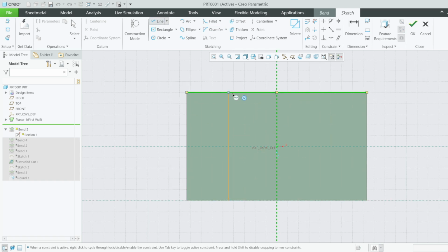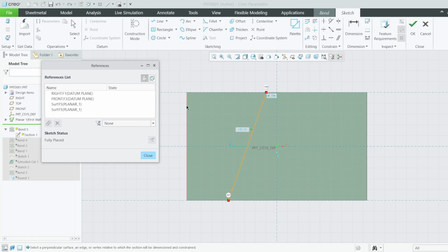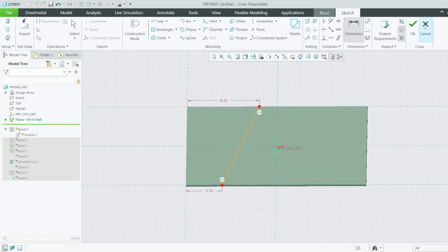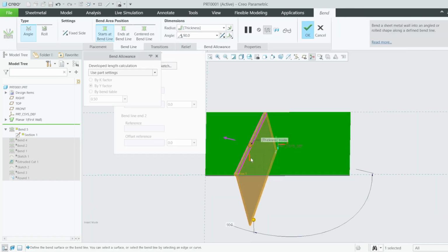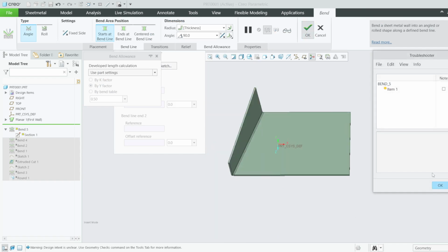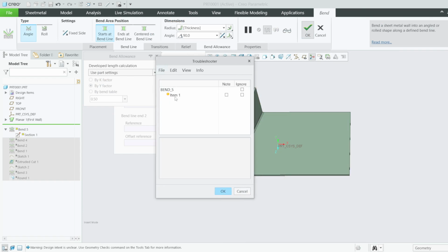You can go at an angle, you can go vertical. Let's now do at an angle this time around. And then dimension your bend line, maybe you want this to be your reference. Dimension from this point to this point. You want it to be 20 from this point to this point, going to be 10. Just note, you can achieve the same thing using the handle draggers. There's no difference. You can see now it's bending downward. I wanted to go up, so fix this side, this arrow. Okay. You can see now we have this here.